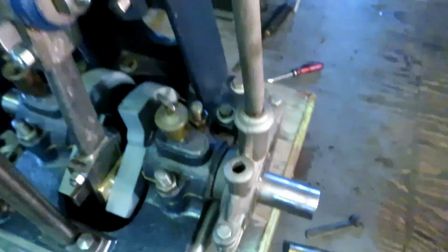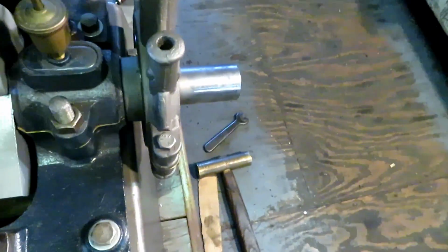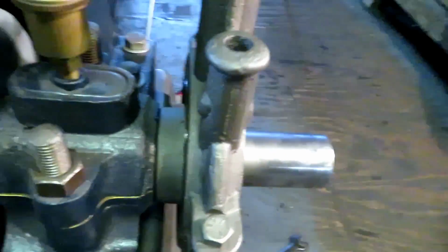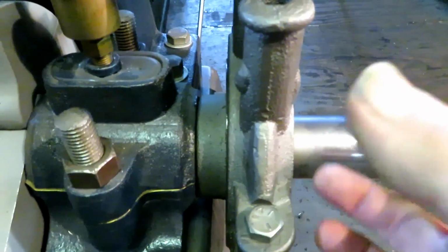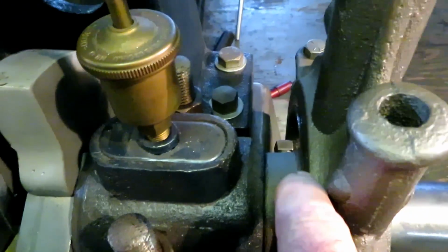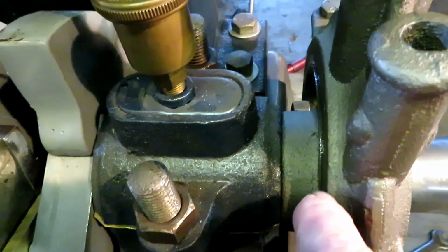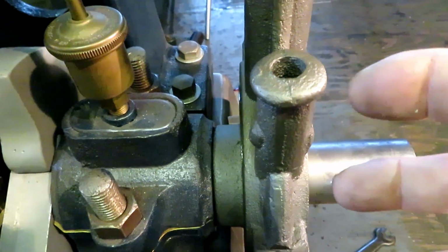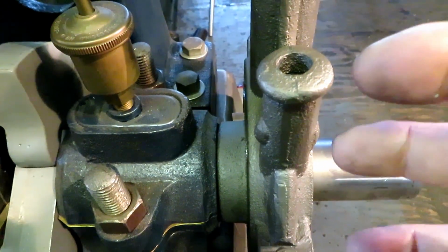And you also at the same time are playing around with the eccentric. The eccentric is never keyed onto the shaft because you have to make adjustments to it. And it's got 2 set screws, big square-headed bolts here. So I've loosened them up and I've knocked the eccentric around a little bit as I was making these lines.